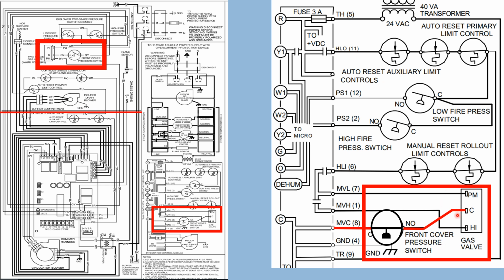If we break this common, we don't need to break both legs of this power, because this is not going to work without that common being back to the power source. And that's why we break that. You don't have to break it twice on 1 and 2. You're just breaking it with the common. And you could apply voltage there all day and nothing's going to happen.